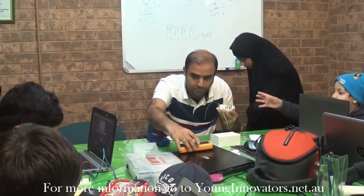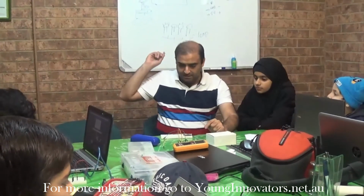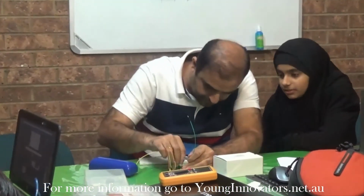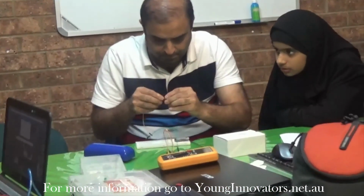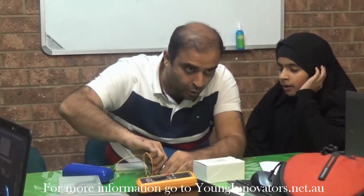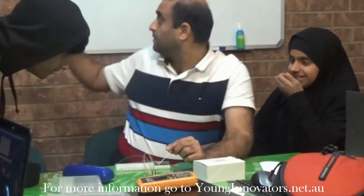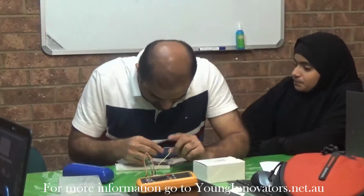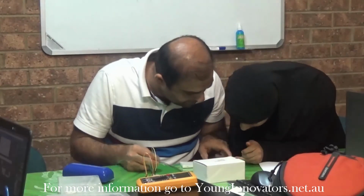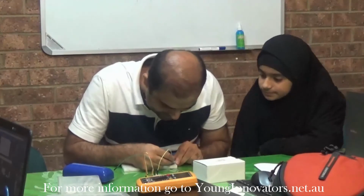Okay, so what are we going to do now? So guys, what we decided, so where will the positive go? The positive will go in the 5 volt. Where is the 5 volt? On which D number? D10. Okay, so where is D10? Can you see D10? Yeah, so it will go right next to D10 here.